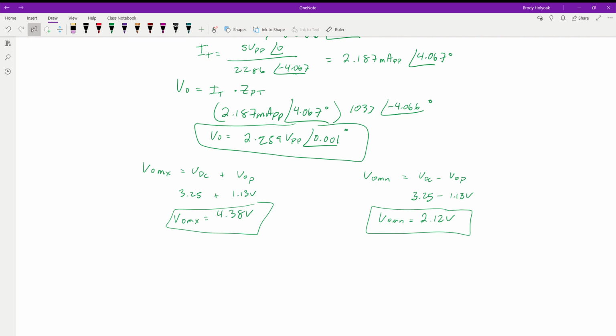We're going to have the most voltage out, and then the voltage is going to taper off again a little bit till it gets down to our critical frequency value, and our angle is going to continue to shift down to negative 45 degrees. So again, those are the patterns that we should see. We should see a plus and minus 45 degrees at the critical frequencies. At our middle, we should see a 0 degree phase shift, right at the dead center between those 2 points.